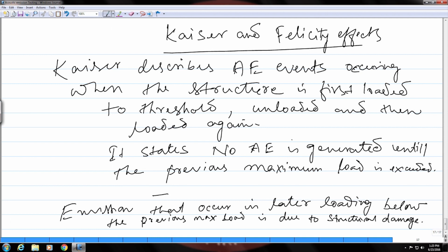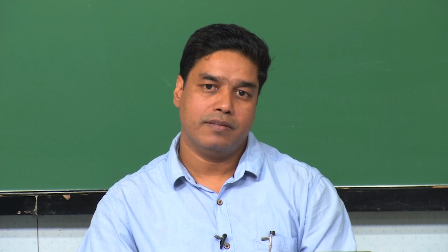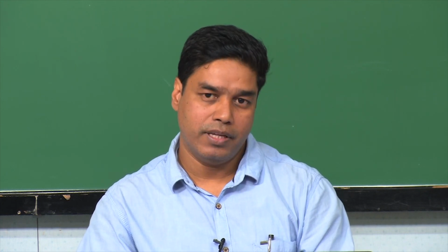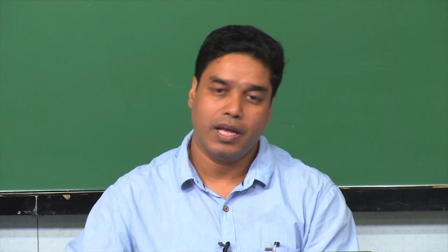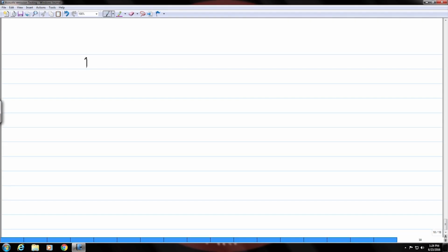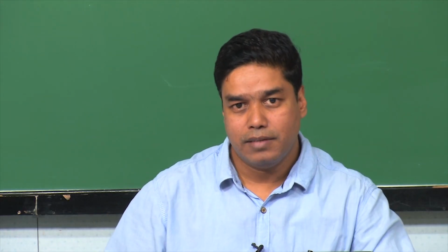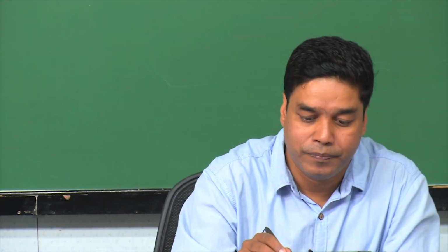Okay, so this is how you get to know the relationship between the acoustic emission events, the loading history, and also whether the structure has been damaged or whether the defects are active or not. Okay. So, this second phenomenon, that is the occurrence of acoustic emissions below the previous maximum load, is known as the Felicity effect. Okay.